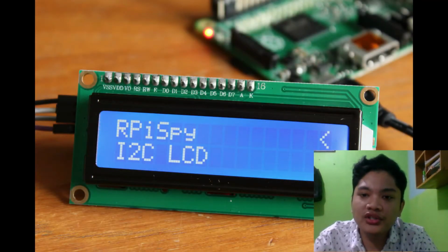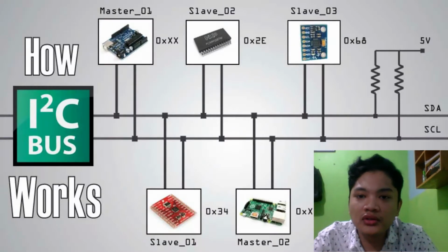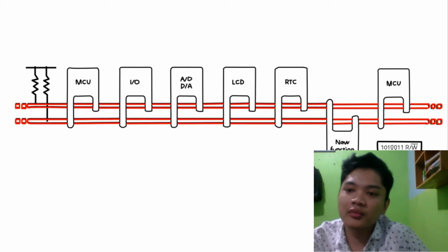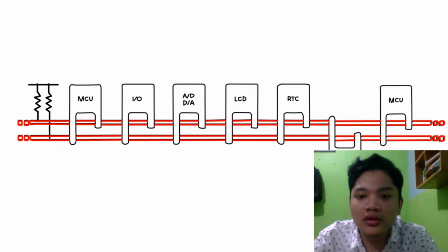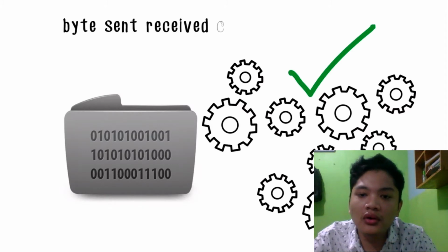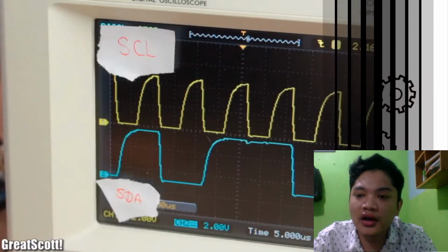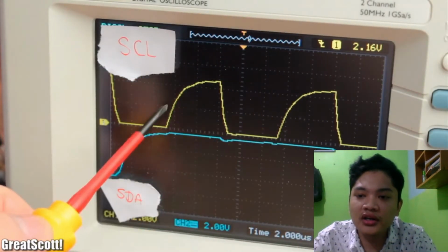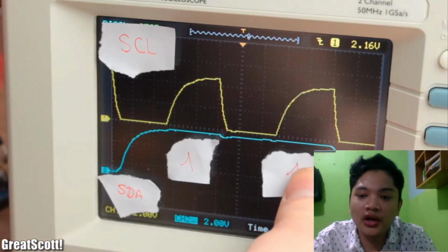Next, I2C. There is also the original and the Proteus library. I2C is a two-way serial communication standard used to channel data, specifically designed for sending and receiving data. The I2C system consists of SCL, the serial clock, and SDA, the serial data channel, which carry data information between the I2C device and its controller.